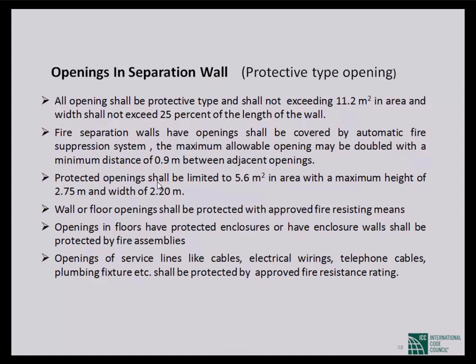Opening for service lines like cables, electrical wirings, telephone cables, plumbing lines, you need some fire protection. In some languages, it is said as a penetration, not an opening. In BNBC, we do not define penetration, but in NFPA, it is defined as a penetration because this opening is small. If you think about the escalator or the lift, that is also an opening through the ceiling, through the roof. But that is a big size of opening. We call it an opening.